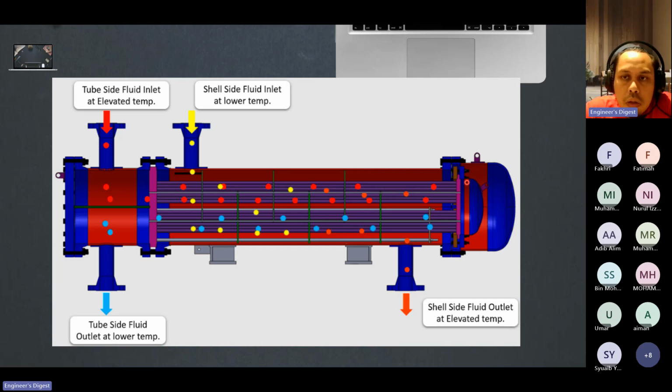For the fixed exchanger, we cannot clean the shell side, but for the floating type we can clean the shell side. How do we clean? This is a backing device. This is a split flange. We can open this. You can see there are two flanges here with the tube sheet in the middle. So this flange we can open, and this bolt we can open. Release this flange, and this whole tube bundle can be removed, and then we can send it to the washing bay and clean. That leaves the shell, which we can clean as well, the internal, and the external of the tubes we can clean also.